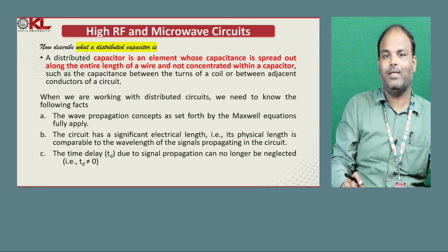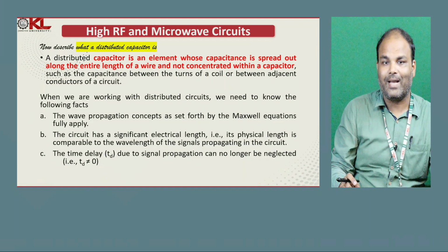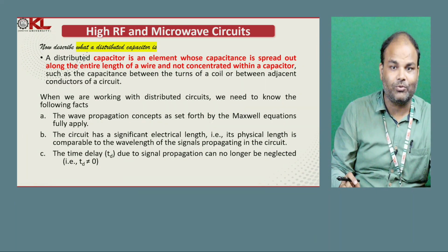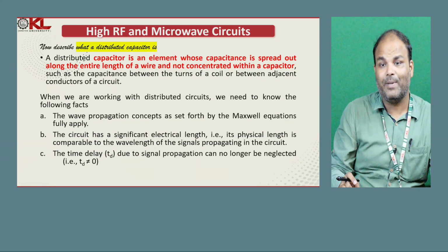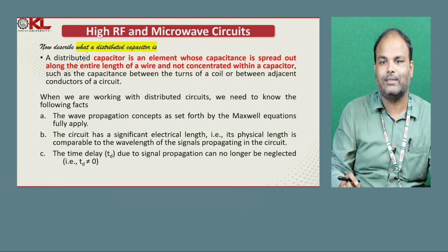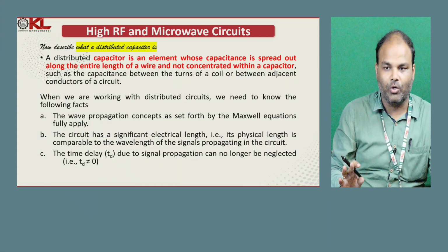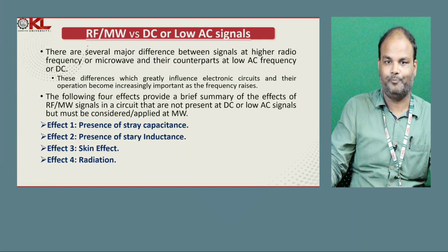Fact one: the wave propagation concept as set forth by Maxwell's equations fully applies. So here we are applying Maxwell's equations. Second, the circuit has a significant electrical length, that is, its physical length is comparable to the wavelength of the signals propagating in the circuit. The time delay due to signal propagation can no longer be neglected. So the time delay we can't neglect.